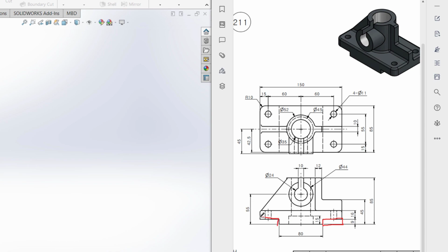is in this way. For drawing this rectangular cut, first of all I'll draw a center line from here to here, and this center line has a dimension of 9 unit. After that I'll offset it to 40 unit each side, as the total distance is 80 unit, and I will then make all the lines construction geometry. Then I'll take the corner rectangle and draw two corner rectangles, one here and another on the other side. Then I will use the extrude cut.